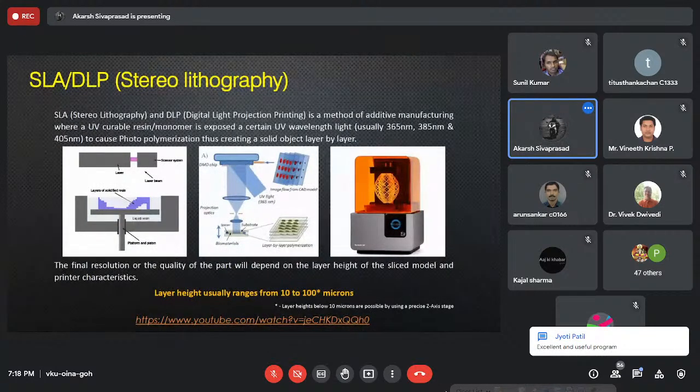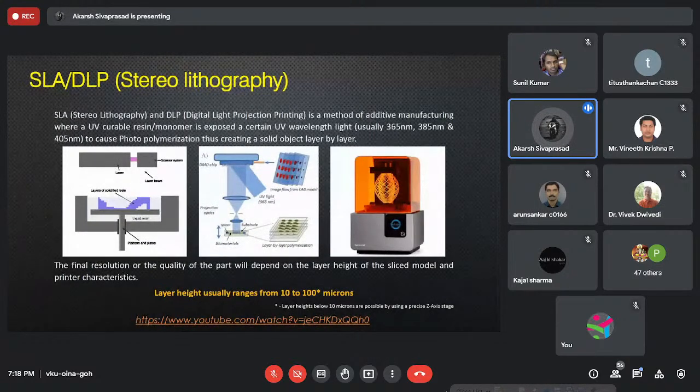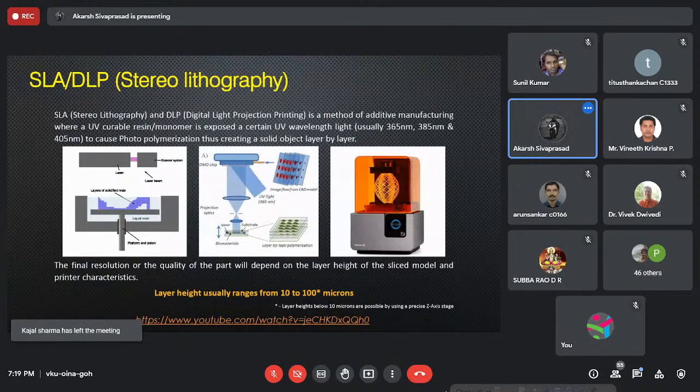Of whatever geometries that you want. In the image on the left, you have a vat filled with this photopolymer, and an integrated elevator or platform piston. You bring the platform all the way up, and then you have the photo-initiating system on top, which is nothing but a laser source and a galvanometer scanner.